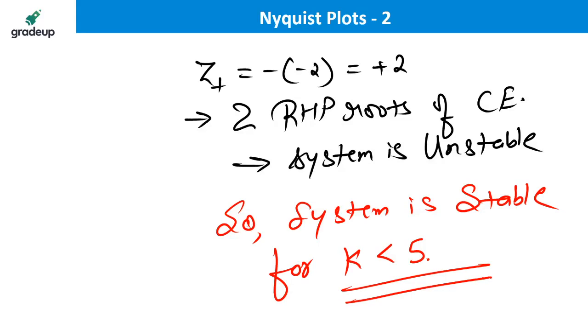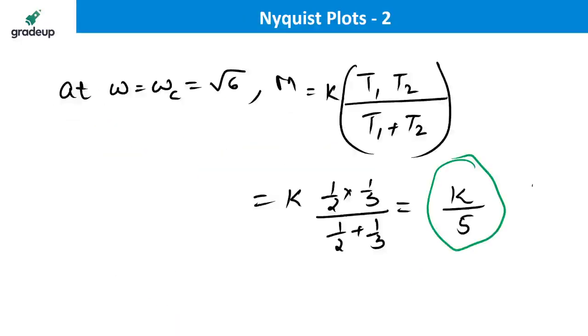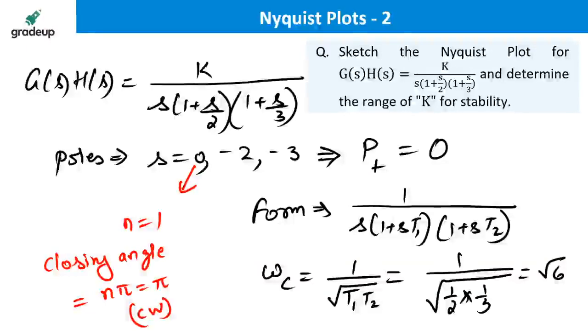Okay. Now with this, I will tell you two categories. I have taken this complete question for a reason. First of all, what happens at K equal to 5? That is marginally stable. Just wait, I will comment on it later. When the Nyquist plot just crosses the -1, 0 point, it is the marginally stable case. Now Z plus cannot be negative. It is impossible; it will never come in a Nyquist plot. Shashanka, I will comment on marginal stability once I start gain and phase margin, when the plot crosses the -1, 0 point.